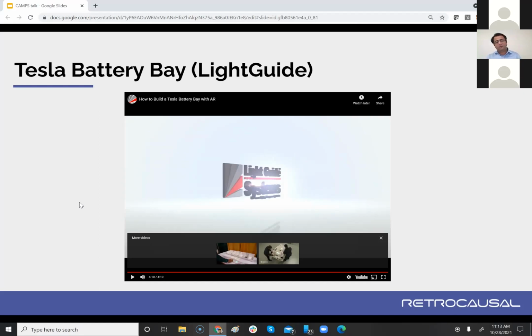Another use case is, I haven't seen a lot of those examples, but in the high mix assembly situation, where workers are prone to making more mistakes, if they have, let's say, 100 SKUs, you might be able to connect these kinds of systems to a manufacturing execution system. So it fetches the current build order, and the worker is able to understand which steps of the activity they're supposed to be doing.